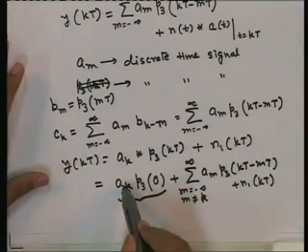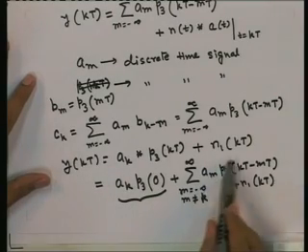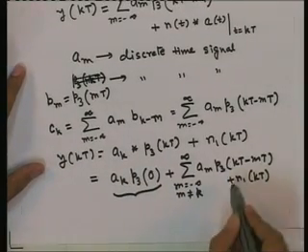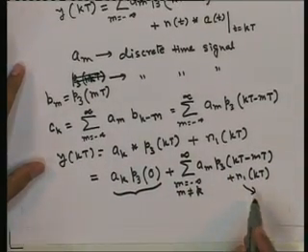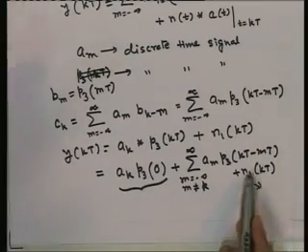So we are going to detect a_k from this sample, but what has happened is all the other symbols are also interfering with this. So this term is noise. We have analyzed this in the context of matched filtering, and we have seen that we can minimize the energy of this. We cannot really eliminate this.